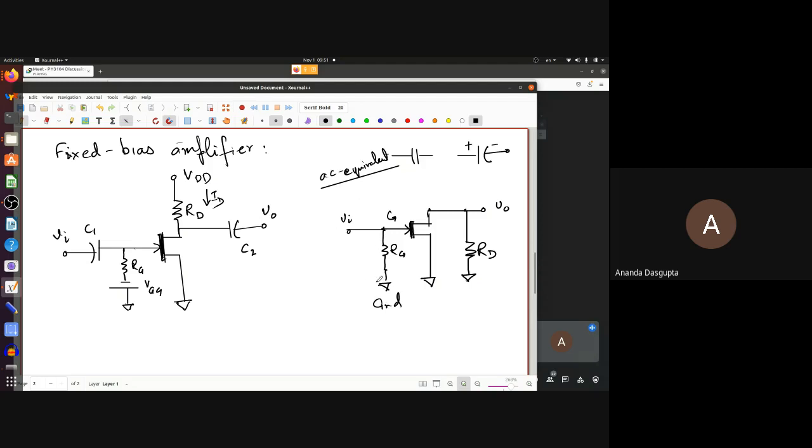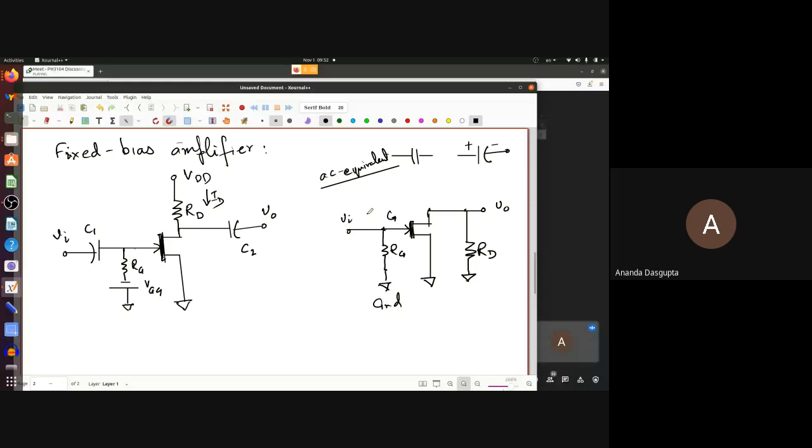Even if that does not destroy your source, which it very well might, it would still drive such a huge current that all the source voltage would drop on the source's own impedance, which would mean that you will get no voltage here. And if you get no voltage at Vi, of course you get zero. So RG is essential for the amplification part, not for the biasing part. But you must have RG.